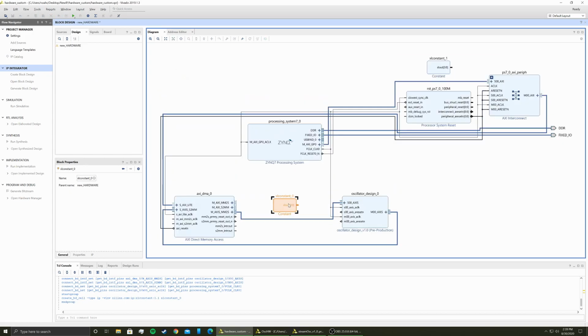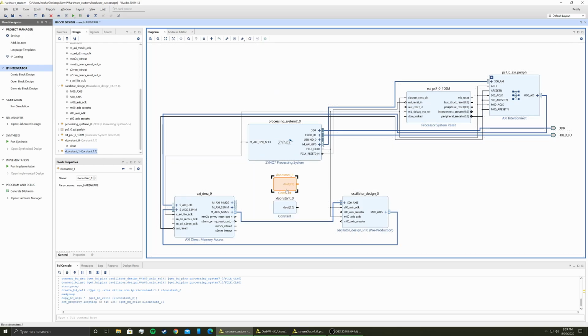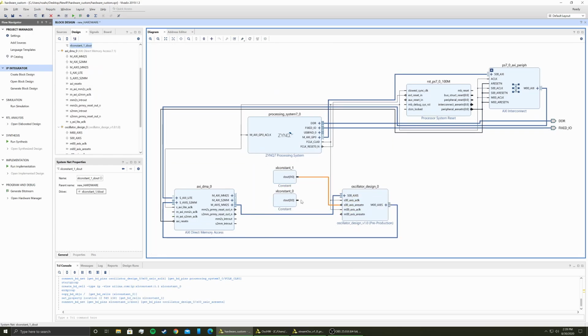We'll just make another copy of this since it's active low. You can just connect it with 1s and it should be active all the time, or you can remove the port in and of itself and it should be good to go. But this is what your design should look like, or if you have different AXI ports.